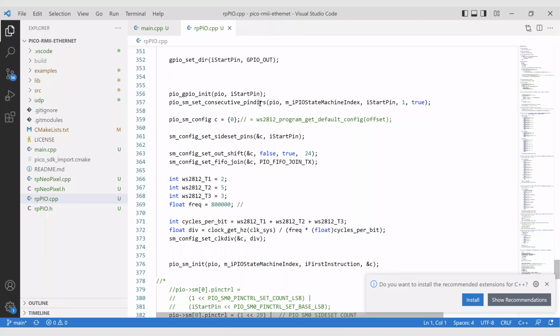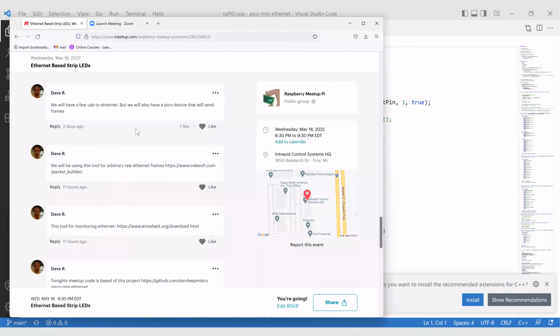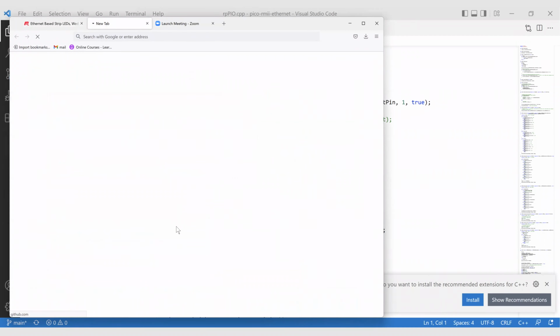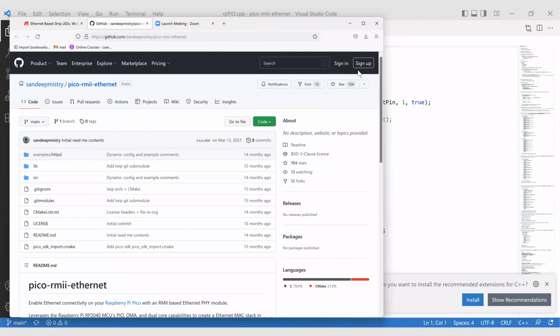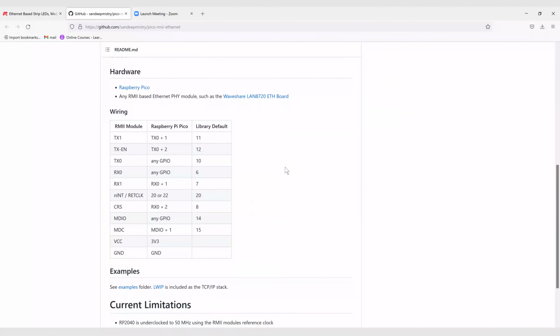If you want to put out 2 bits, it has to be like bit 1 and then the next bit. So it has to be in GPIO order. A common mistake designing boards around PIO is that, and I can give you an example. The code that this Ethernet project is based on is from this guy Sandeep, which is pretty cool. But if you look at the pinout, he has...